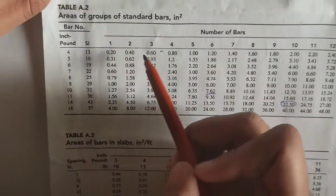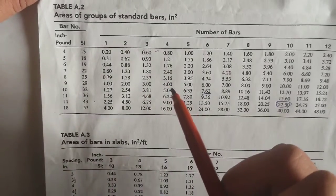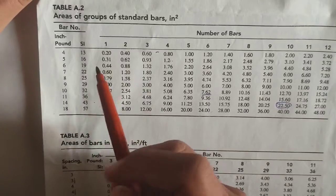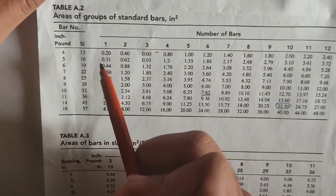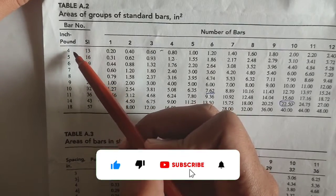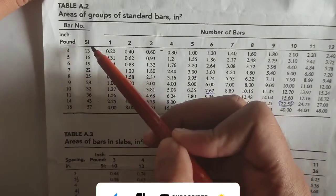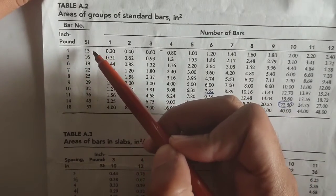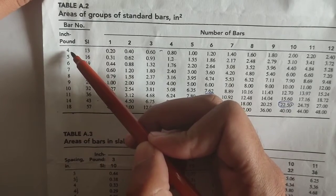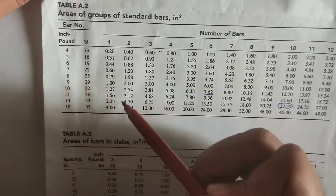So we have this table, which will be used for beams and columns. I am telling you about structure elements. For beams and columns you will use this table. In the first column you have the inch pound bar designation number from 4 to 18, and in the second column its equivalent system international bar designation. For example, if the inch pound designation is 4, the same designation for the system international unit will be 13.